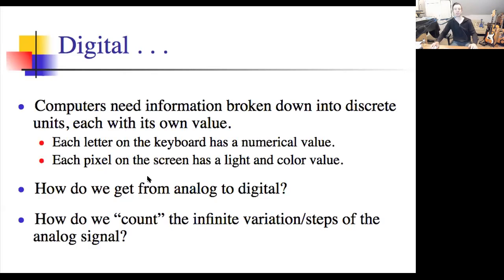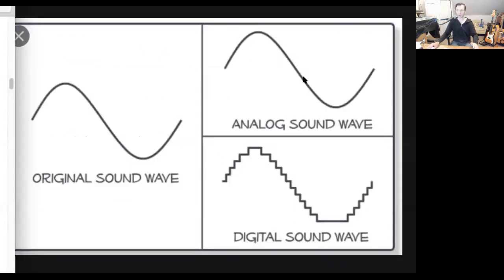The first thing we're going to mention here is sample rate. Sample rate is how often you take a measurement of the incoming voltage. When we look at this waveform, now looking at the right side here, you see that the voltage in this diagram is changing, right? That voltage goes up and then it comes back down. This could be far more complex as a waveform, but in the digital format, we only have zeros and ones. So we're defining values in a stair-step pattern that we can record, literally like an Excel spreadsheet.